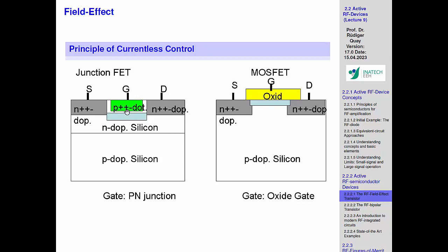And that's something maybe that helps you also in the understanding. When we have a MOS cap, we only have the capacitance based on the field effect, so to say. While if you have a PN junction in there, there's also the junction capacitance, which adds. So it's very simple. The junction things are very slow.